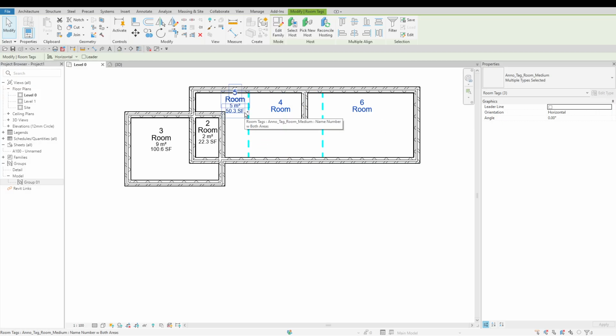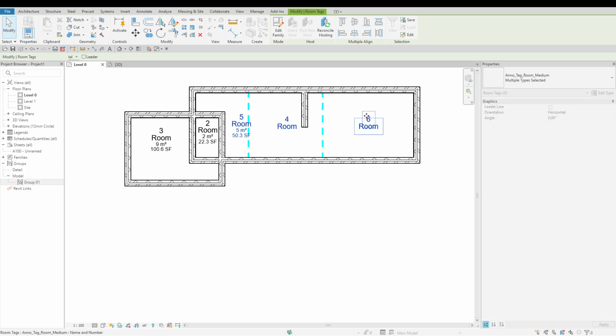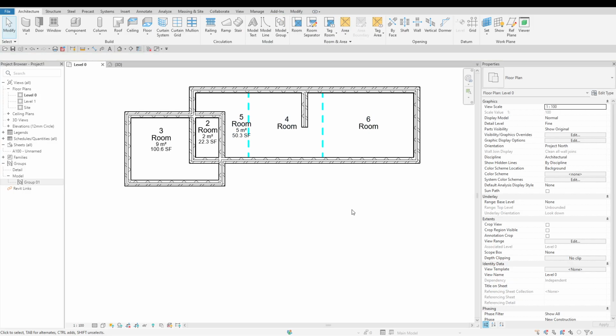When exporting project information to a GBXML file as an analytical model, any spaces not typically classified as rooms, such as attics, shafts, chases, or the space between floors and ceilings, must be included in the overall volume of the project. In addition, rooms should be defined from the center line of bounding walls and from floor height to floor height to ensure there are no gaps between building spaces.